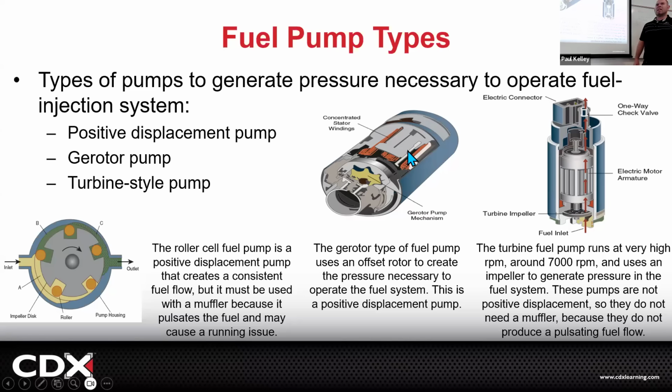I believe it had eight segments in the motor. On 6 or 7 of them, they looked clean. And then on 1 or 2 of them, it was kind of flat. So it's almost like a V8 running on 6 cylinders. The problem was that the fuel pump would speed up and then get to the dead segment and slow down. If you ever notice with a cordless drill, you grab it and squeeze the trigger and you notice it struggles?